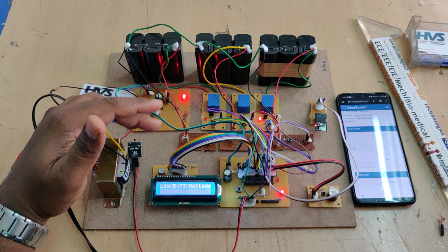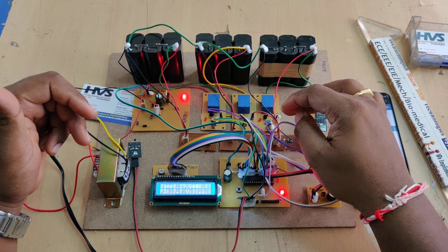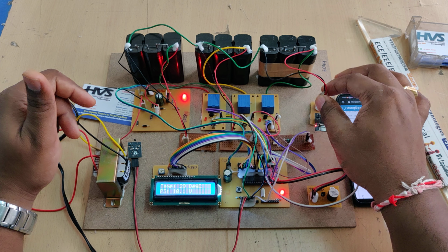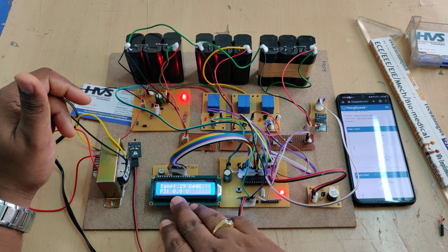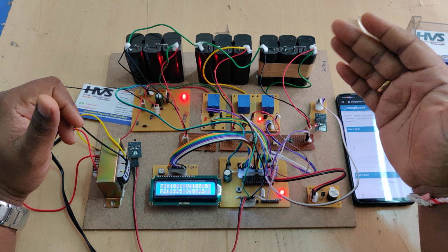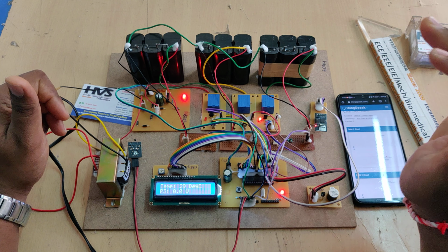If the relay is continuously switching on and off, to make the battery fully charged, just disconnect the respective battery pack from the voltage sensor. Then the system will treat battery pack 3 as having low voltage and will keep on charging. You can just leave it for 10 minutes, and then automatically the respective battery pack will become fully charged.